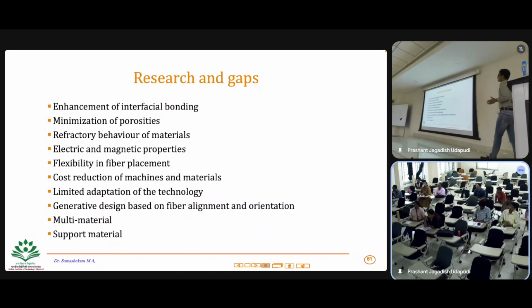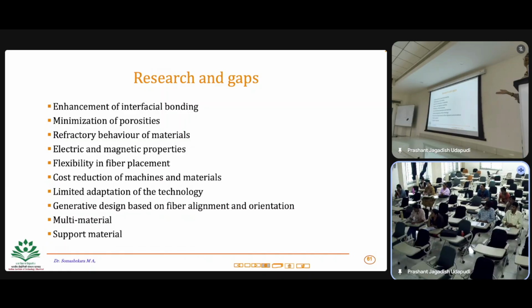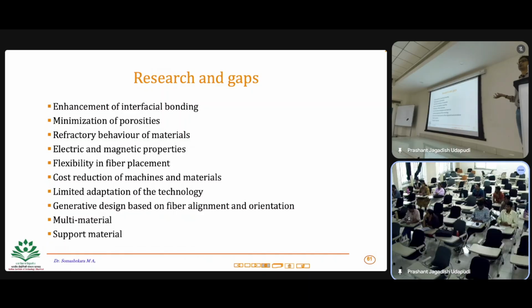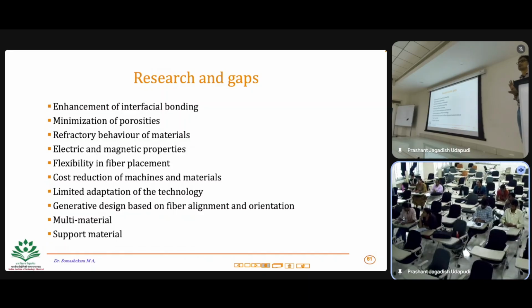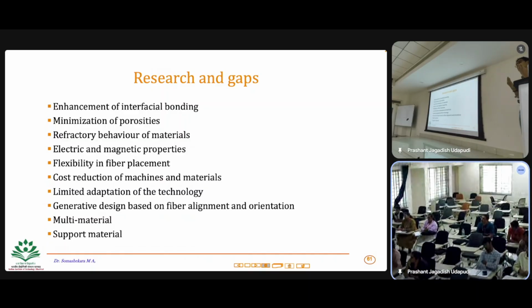In many cases, these problems happen when you have a large temperature difference, right? For example, your printing temperature is say 100, but your surrounding temperature is 30 degrees Celsius. Then you will obviously see a huge temperature difference between the nozzle and the bed, and definitely your part may not go well. It will quickly solidify, quickly cure off, right? So you need a controlled surrounding so that you get the quality of the part.